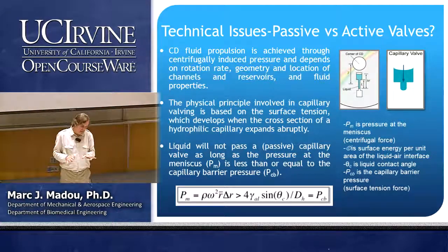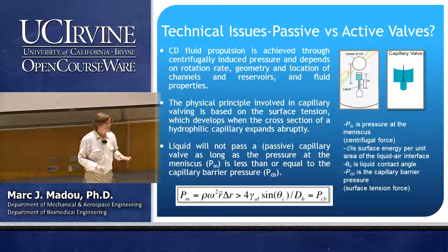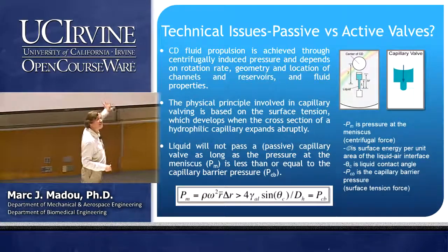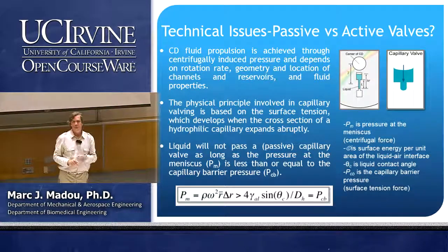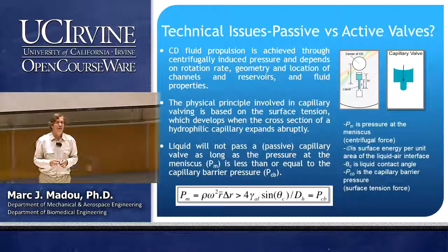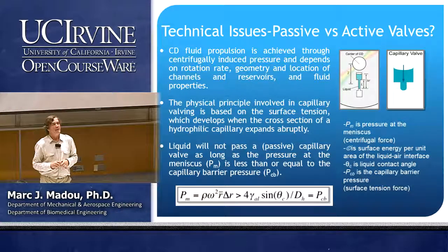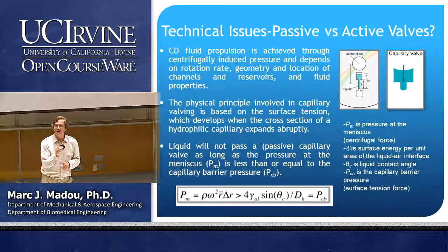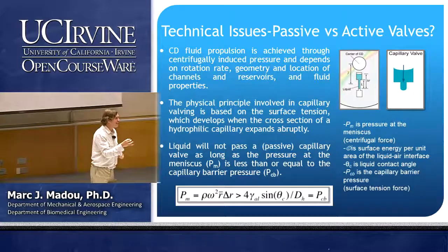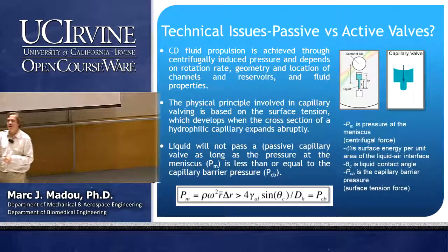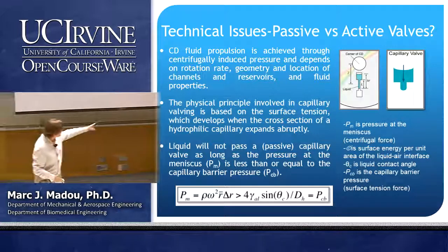And so we see now companies that are implementing some passive valves where they can, and some active valves, trying to make clever combinations. Our own group, and I will show you that on Tuesday, has started developing alternative valving methods. And maybe by Tuesday you guys come up also with some other ways on how to do it. Don't do it with mercury. So often I hear, put some mercury there, because then you could kind of have that liquid metal removed perhaps, but who wants mercury in a medical device? I don't think you would be very welcome. But come up with some intelligent alternatives for that problem there.